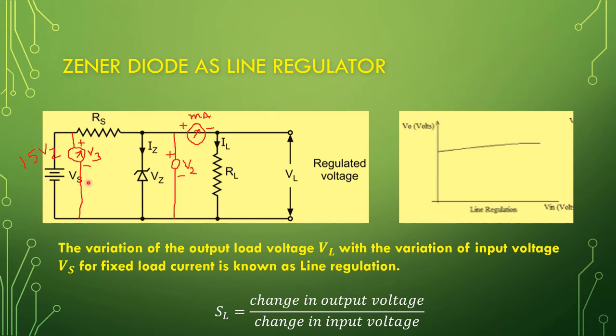Check the constancy of the load current at each step, and if necessary adjust it to the chosen fixed value by changing RL. So here we fix the current meter at 10 milliampere or 20 milliampere.